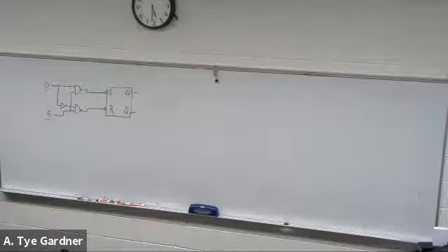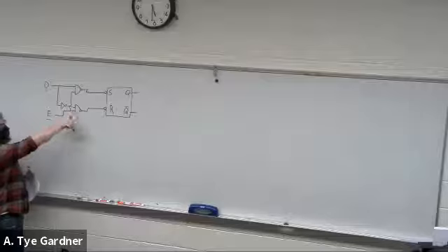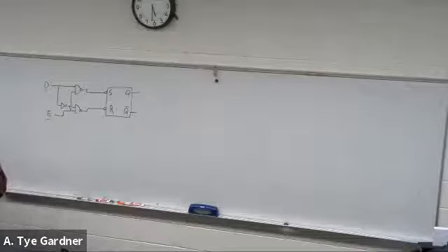And we make sure it's robust by taking the D, the data, and inverting it and putting it into reset. So that by design, we can never have set and reset at the same time.